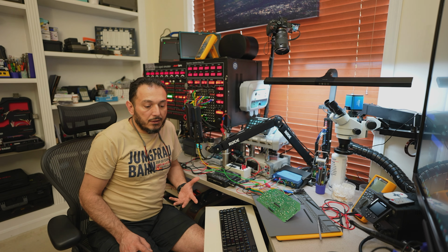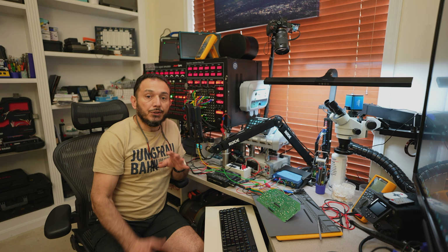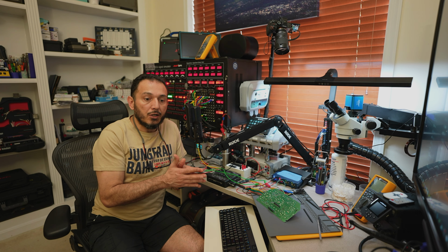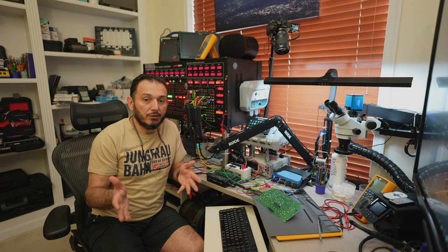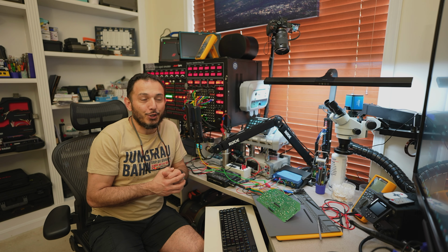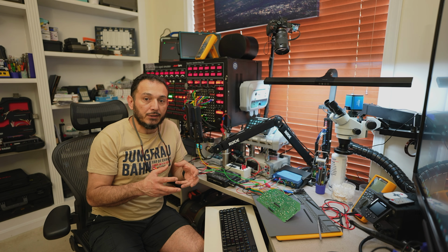Alright, so these clusters are coming here because they have problems. The actual cluster is working perfectly, but there is a signal that goes through the cluster, coming from the ABS module and reaching the ECM through the cluster. Don't ask me why Toyota did that, but it's just the way it is. And it sets a fault code of P0500.